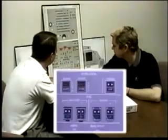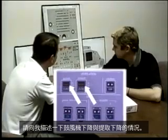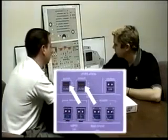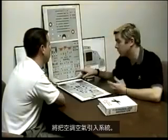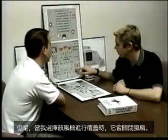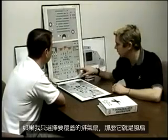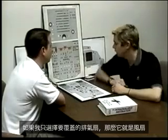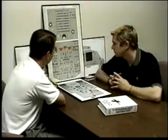Ventilation. You have a blower and extract. Describe to me blower fault versus the extract fault. Well, first of all, selecting either one of these to override is going to introduce air-conditioned air to the system. However, when I select the blower to override, it's going to shut the fan off. It's an on-off switch. If I were just to select the extract fan to override, then the fan is going to continue to run. It is not an on-off switch.